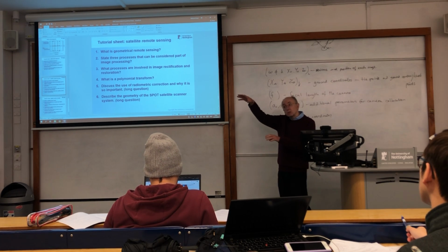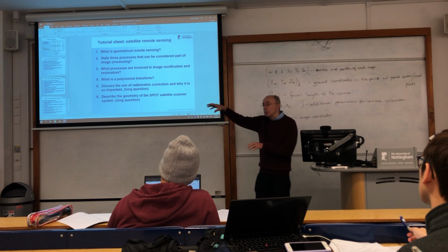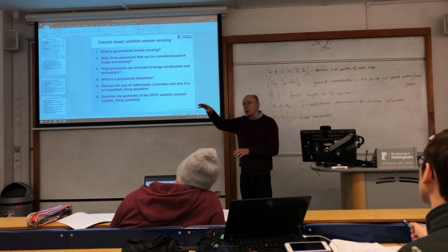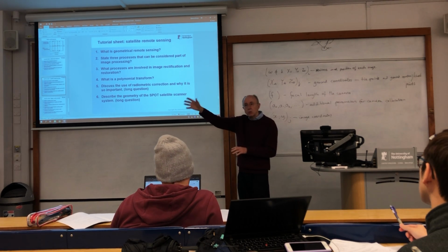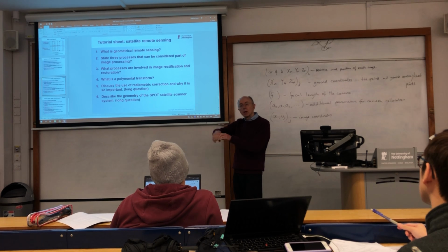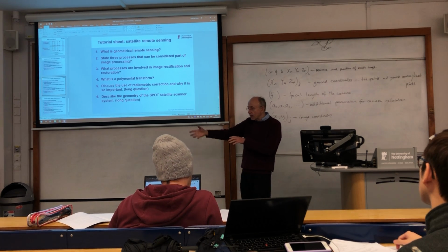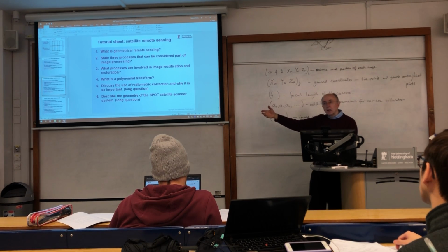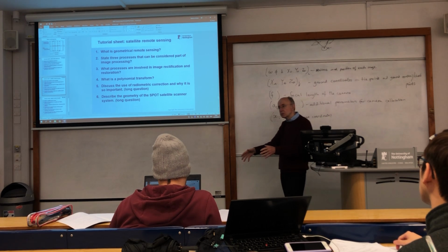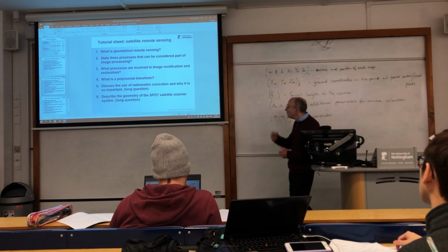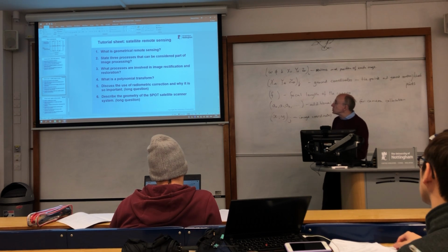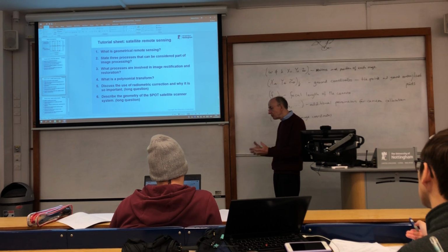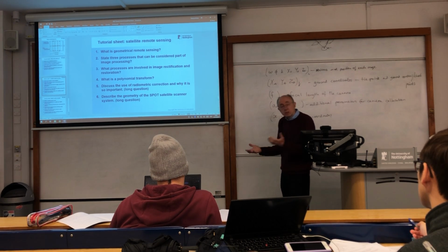Then when you get the remote sensing image, you can go into that image and say everything that's of this spectral band, let's call it a colour, like blue, everything that's blue, you can recalibrate or recorrect it by applying a correction to make it a different colour that's based on the colour that you picked up on the spectrometer in the field. So it's really more to do with not the geometric correction but the image, what the image looks like in terms of its colour.